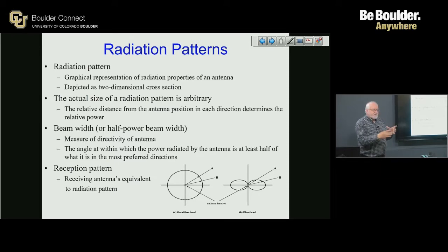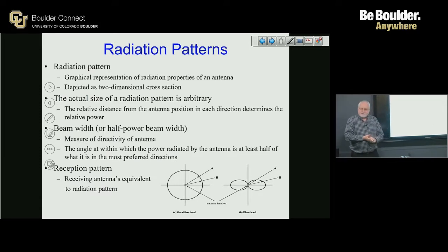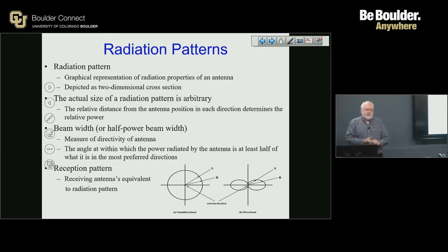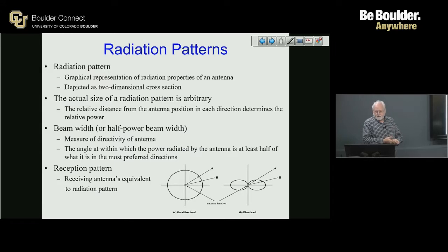Omnidirectional antennas that have either hemispherical or donut-shaped coverage are very useful for access points. An isotropic radiator actually creates a spherical wavefront, so it's omnidirectional in 3 dimensions. So you can think of antennas being either omnidirectional in 2 dimensions or in 3 dimensions. Generally speaking, I can't think of a good counterexample: a receiving antenna's pattern is the same as its transmitting pattern. In other words, the gains are the same whether it's transmitting or receiving.